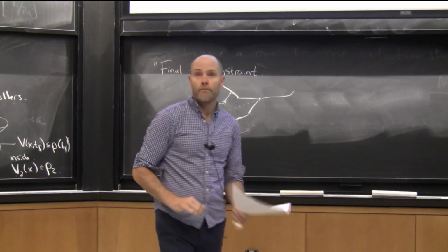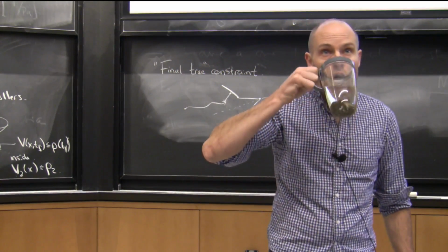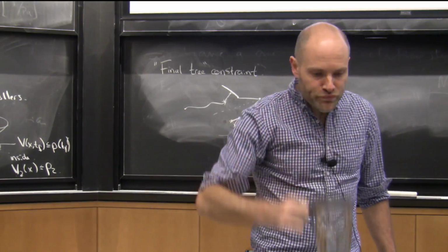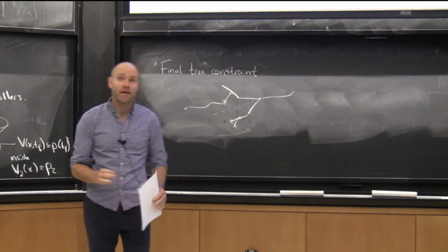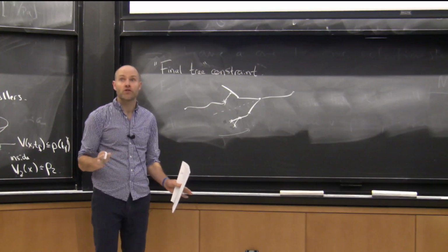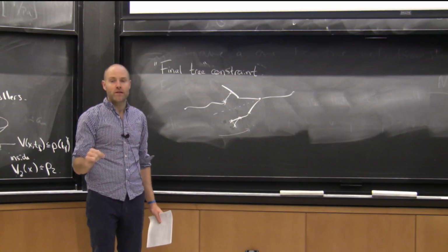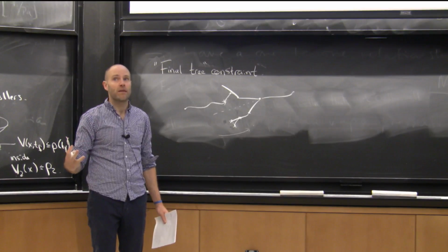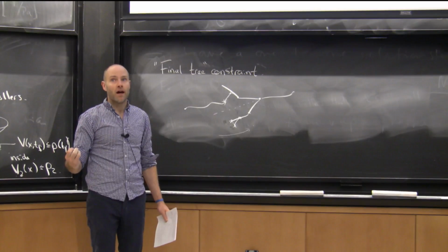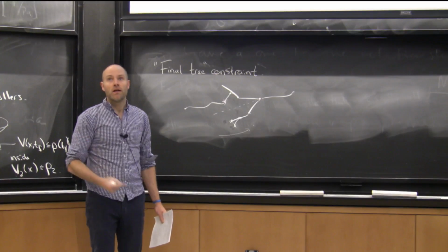So going to any point along the tree seems like the core constraint. Does that mean that these are sort of mixed integer problems, not so much linear? You could potentially do better by explicitly telling it that there's a combinatorial choice. But the same way we can do trajectory optimization through contact by just giving the complementarity constraints as a nonlinear constraint and hoping SNOPT will do its job, or you can explicitly tell the solver and get a more complete algorithm.